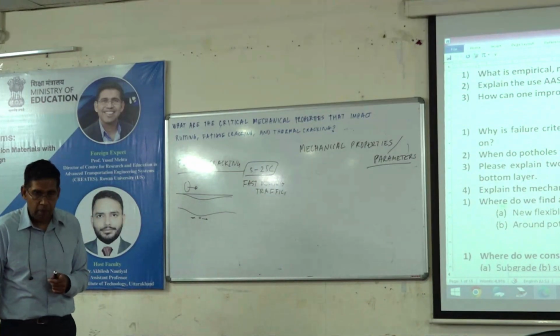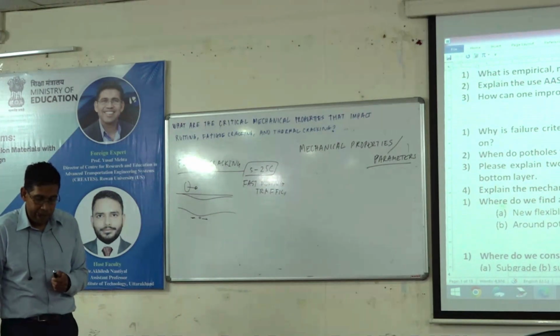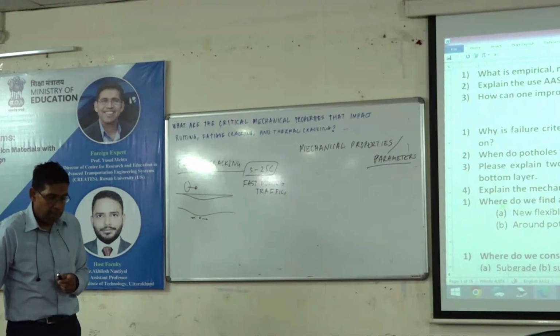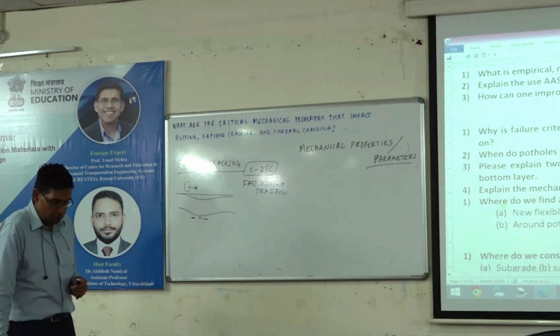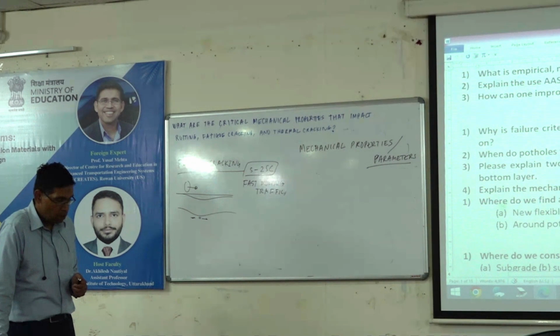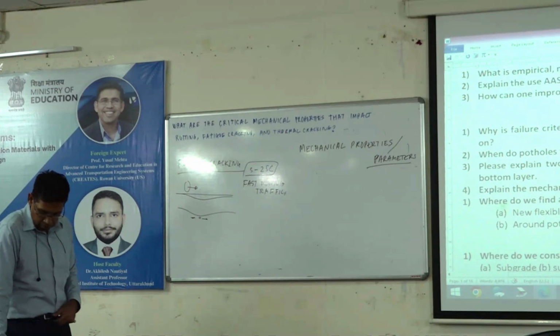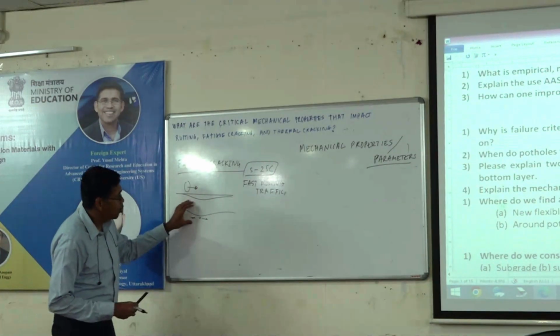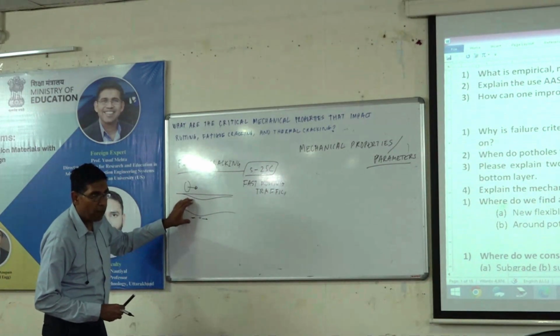If you use unsuitable bitumen for a location, for example, if you should use soft bitumen in a cold region and you use stiff bitumen in that region, you will get fatigue crack.